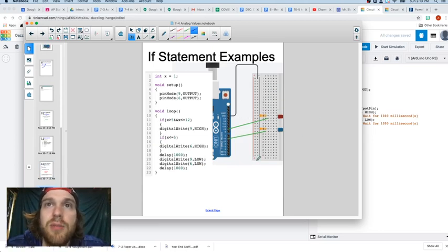So this is a perfectly fine program. I don't have to charge the power rail here. I got a red LED and a blue LED. I've chosen the number 1 for x, and x equals 1. I'm set up now for port 9 and port 6. Remember to do both because some of these programs require multiple LEDs. If x is greater than 5 and x is less than or equal to 12, then I turn port 9 on. If it's less than or equal to 5, I turn port 6 on.